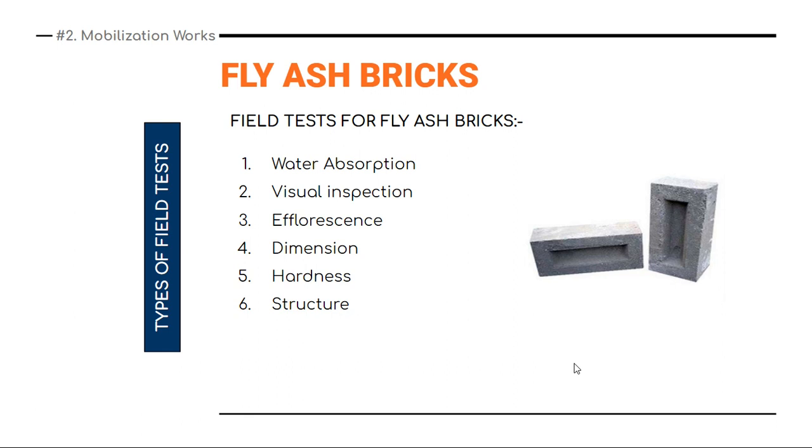After that pressing only, you get good quality fly ash bricks with a very uniform shape. So CPWD has guidelines for that. If it is hand molded, then reject it immediately. Go visit the fly ash brick factory where it is made. If they're using proper CPWD guideline machinery, then only purchase fly ash bricks from them.